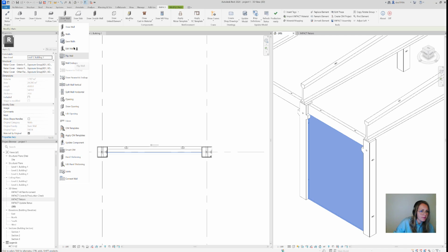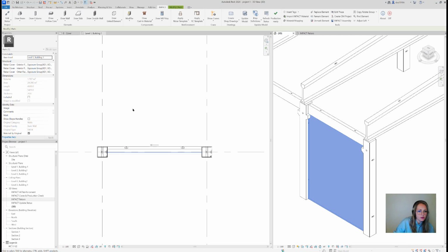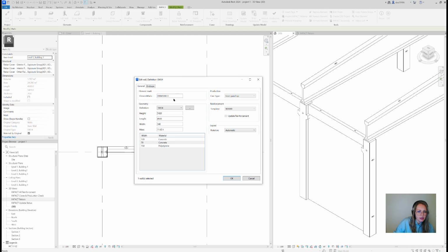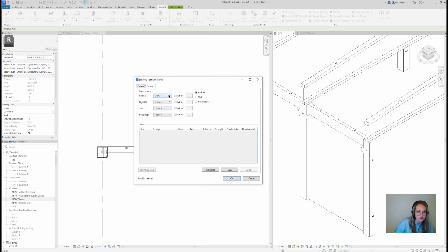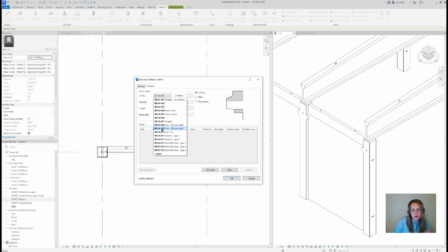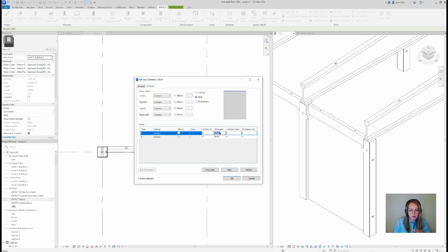geometry editing. Okay, what you need to do now is to go on the edit wall command. So I'm gonna mark the wall, go to edit wall, and here there are some end caps, which is basically deciding the end geometry. We're gonna focus on that in a while. But this is what I want to show. That's the other end caps, and it's a pretty powerful tool because if you switch on the wall preview in here, you can actually get a live picture of what you're doing with this.